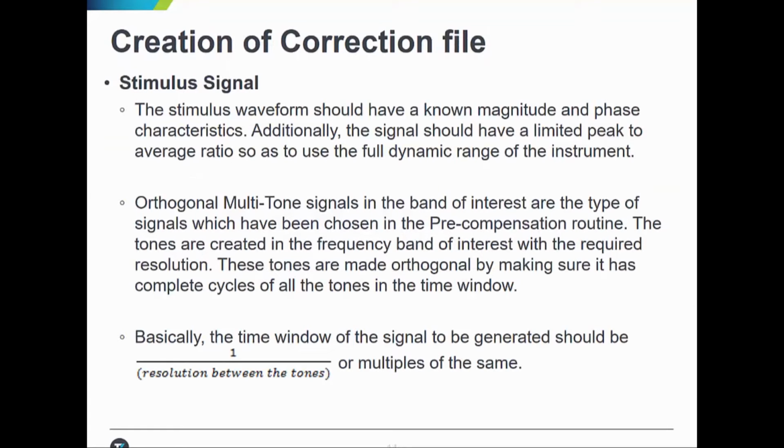The instrument performing the acquisition of the signal should have a bandwidth higher than the band of interest. The capturing instrument should not add any of its own artifacts or distort the signal which would be characterized. Thus, a near ideal capturing instrument would be required. Tektronix wide bandwidth oscilloscopes suit these requirements. Scopes with sampling rates as high as 200 gigasamples, bandwidths up to 70 gigahertz, and analog to digital converters are ideal for doing this type of compensation of the AWG signals. The scopes also provide the ability to capture large record lengths, which will give better frequency resolution for the analysis.